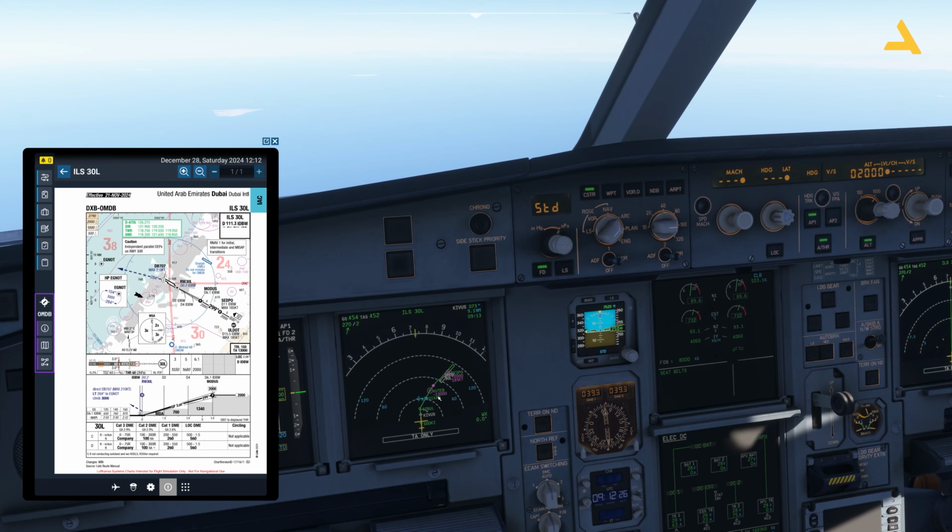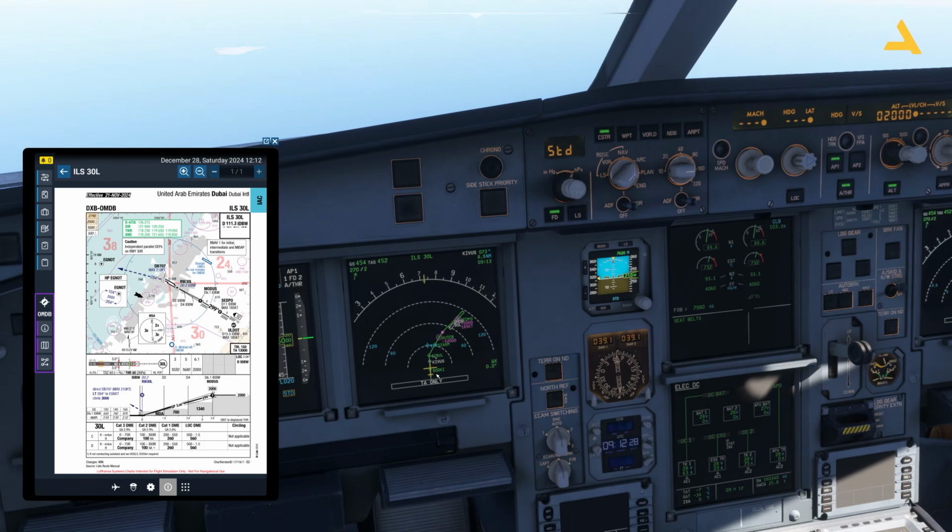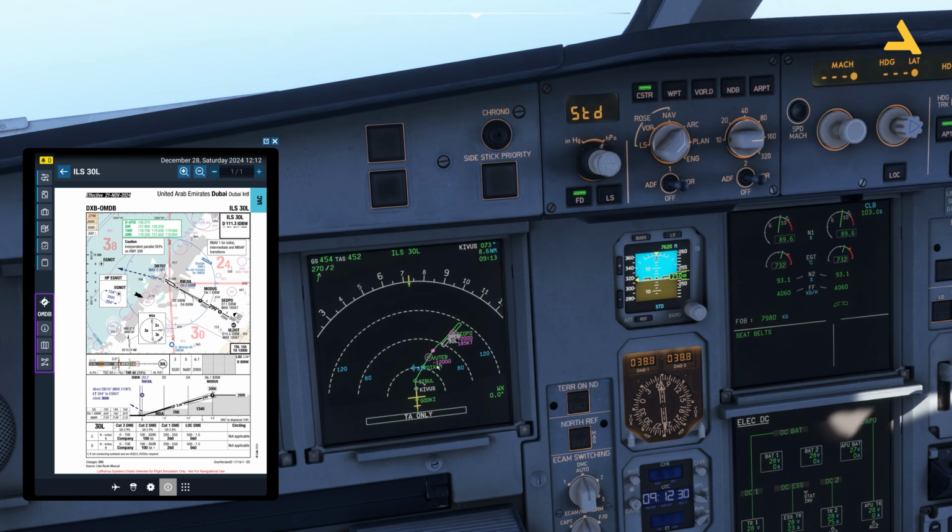We can just look at these constraints over here on the screen. As you can see at this point, the plane should be below 12,000 feet, or at 12,000 feet, as it's minus. So 12,000 or below is acceptable. So almost like 50 nautical miles away.